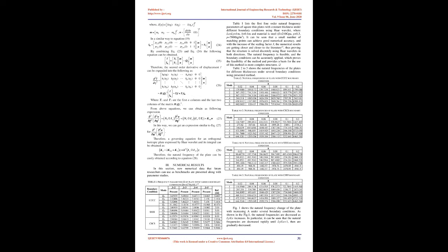follows in matrix form. Considering the boundary conditions, it is easy to know that f is a zero vector with a length equal to 2n, and it will be omitted. E is the unit matrix. Similarly, the following expression will be used to calculate the Haar wavelet expression of the fourth order mixed partial derivative of w. If g dot equals the second partial derivative of w with respect to x, the second derivative of g dot along the axis can be approximated by Haar wavelet. By integrating the second derivative in turn, the following expressions can be obtained.